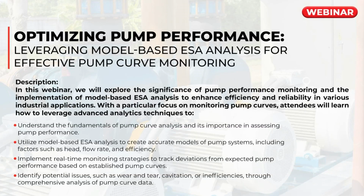So for those of you who are already aware of the capabilities of model-based electrical signature analysis, you know that through voltage and current, one can monitor the rotating asset, whether it's a pump or fan or conveyor or compressor. And with that, you can see the electrical issues, whether it's on the power circuit or incoming power, or through the mechanical components of the rotating asset. This includes the electric motor itself, the drivetrain, and the driven equipment.